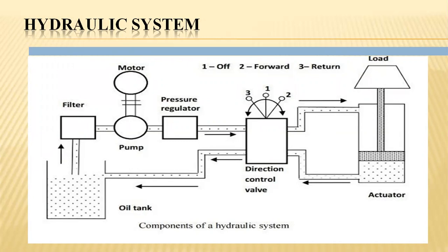In the previous class we saw the different directional control valves. There are 2x2 valves, 2x3 valves, 4x4 control valves, 4x2 way control valves, like that. Preferably, we'll be utilizing 4x3 way control valves. So 4 ports and 3 positions will exist, and the middle one will be the null position, the left one will be the forward stroke condition, and the right side position will be the return condition. So hence 3 positions. See here, the first position, the middle one, there is an off condition, which clearly specifies there will not be any connections to it.